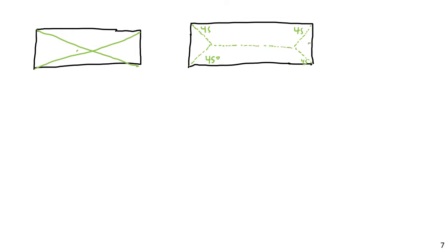So you have two triangles on the ends that go to the narrow ends. This triangle will go to this beam, this triangle will go to this beam, and then this trapezoid and this trapezoid will end up going to the beam at the top and the bottom. The whole idea is that once you have this area, you can then multiply by the area loads to transform those into loads per foot, pounds per foot, kips per foot, that sort of thing. So maybe I could run through a brief example here for, say, a one-way loading.